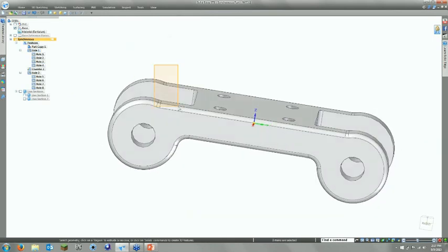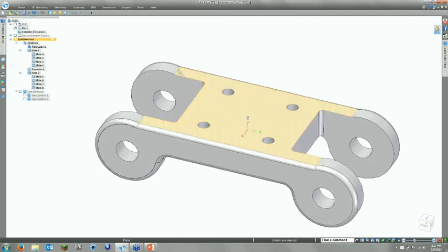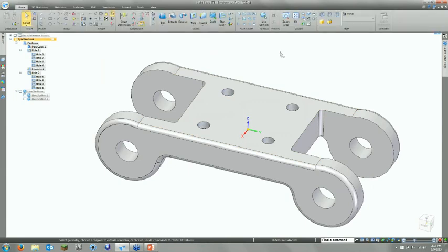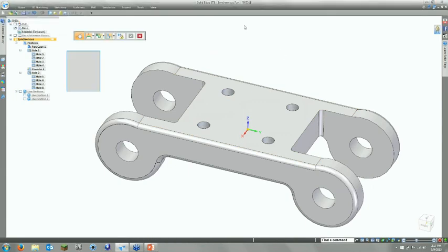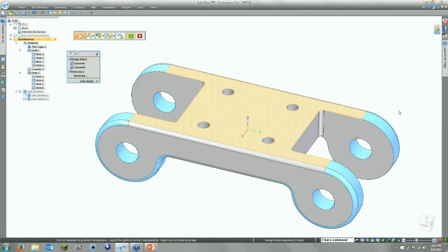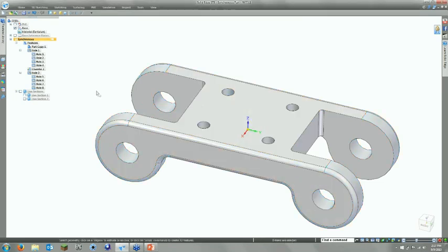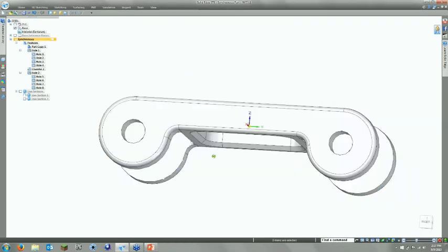All right. Don't need these radiuses on top now because I'm actually going to use a relationship again to make these look exactly right, because I want these tangent to this face. So I'm going to let my design intent come into play doing this. I'm going to come over here and make a relationship between this face, make it tangent to this face, and only have to do it to the one face because design intent is going to interrogate the geometry and say, hey, it's exactly the same as these other sides and this other corner, so let's make them the same. So I didn't have to go and reapply a relationship to all those.